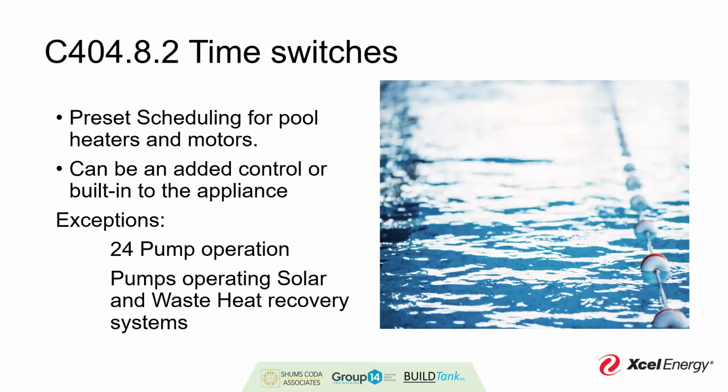For time switches, again, we're tying back to our pool heaters, our pool monitors. These can be built into the appliance, and that would be considered appropriate. Or this can be an added control that's somewhere in stream, so to speak, of the control process here. You have two exceptions that you're allowed to not have to worry about this for, which are 24-hour pump operation related pools, and then pools operating solar and waste recovery heat systems.